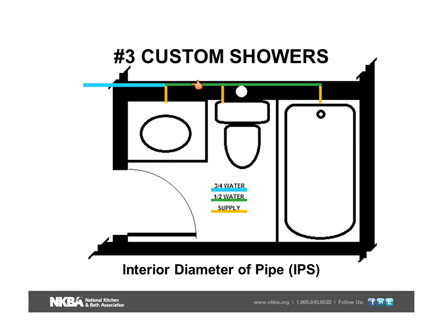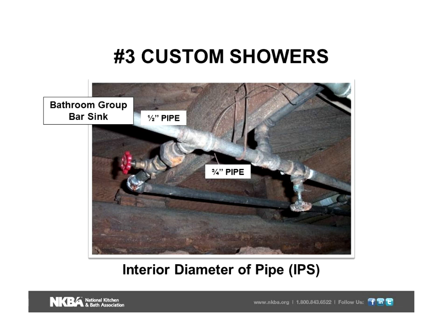But the problem is, and again, I'm using a very small bath here, what happens if we decide to turn this into a custom shower, or we decide to upgrade the filler to a 3/4 inch tub valve? If we do, we've got a problem. We'll not get the water we need through a 1/2 inch water line. So you sold a very expensive filler, and it's going to fill the tub at the same rate, or provide water into the shower at the same rate as that 1/2 inch water line did to start with.